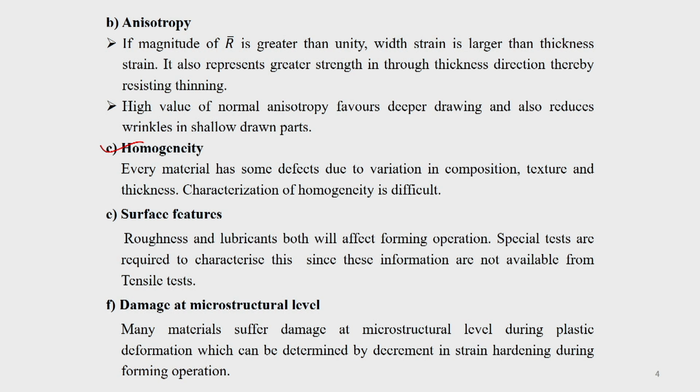Only by visual observation or observation under a microscope you can say this is better homogeneous, or maybe through a microscopic technique like X-ray elemental mapping and other things you can say it is homogeneous, better homogeneity is there. But there is no quantification, so that way characterization of homogeneity is very difficult, and that varies from person to person who is doing the analysis.